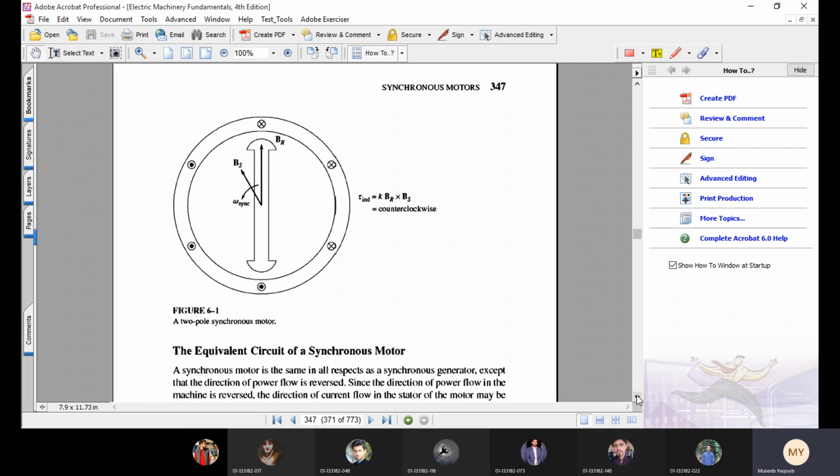What is that special circuitry? Actually, a single-phase motor can never rotate unless a special starting scheme is provided to it. For example, in the motor installed in your ceiling fan, you can observe that there is a small capacitor installed near the motor.